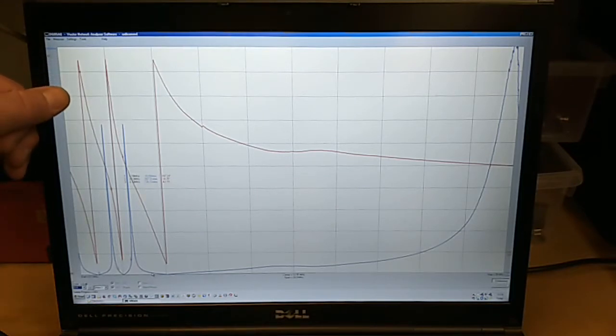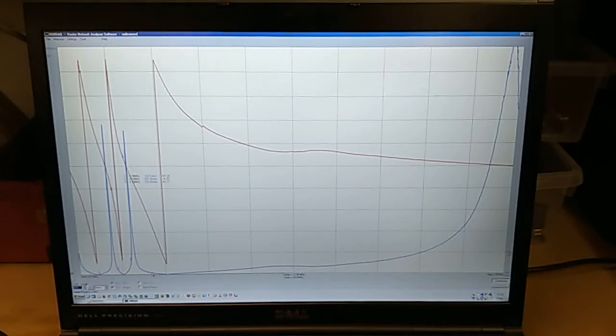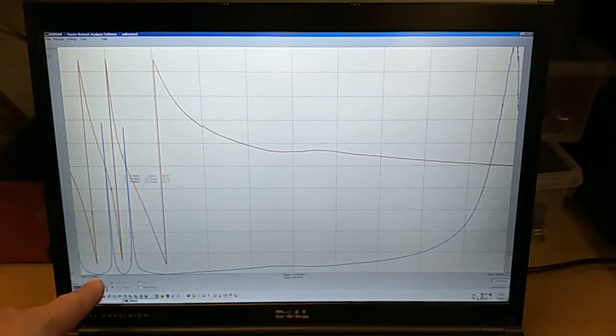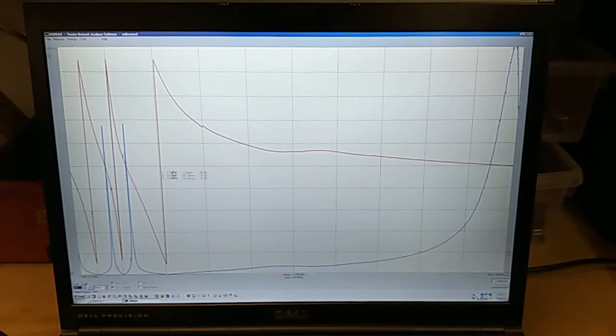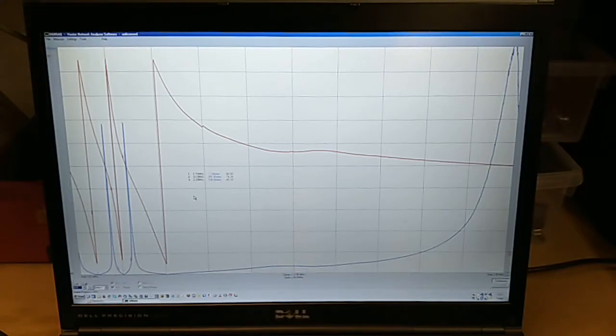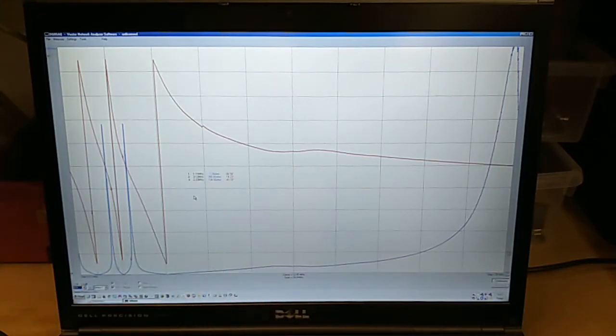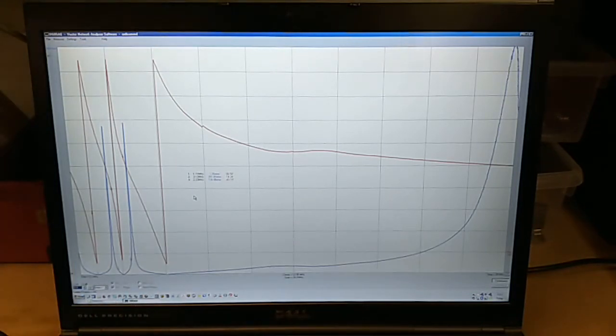So we've got a phase change down here at, let's have a look where that was. It's a series resonance. The impedance there is very low, so only about 1.26 ohms at the bottom, and at, let's just move those a little bit so we can see them, 1.11 megahertz. So it has dropped very slightly as a result of the pressure of the primary starting to push on those other resonant circuits as they come in close resonance together.